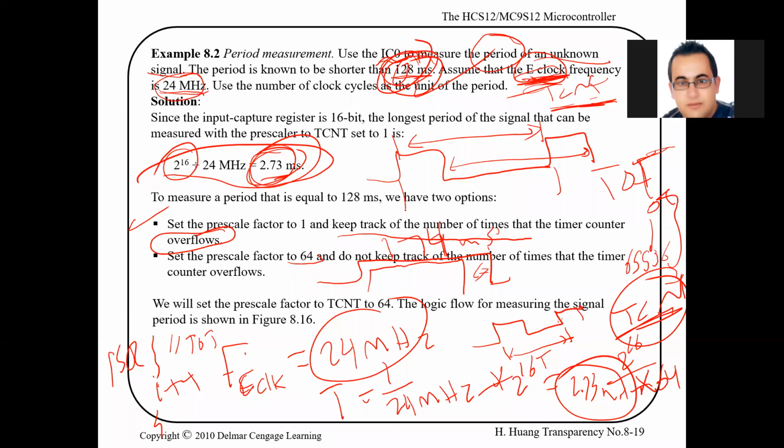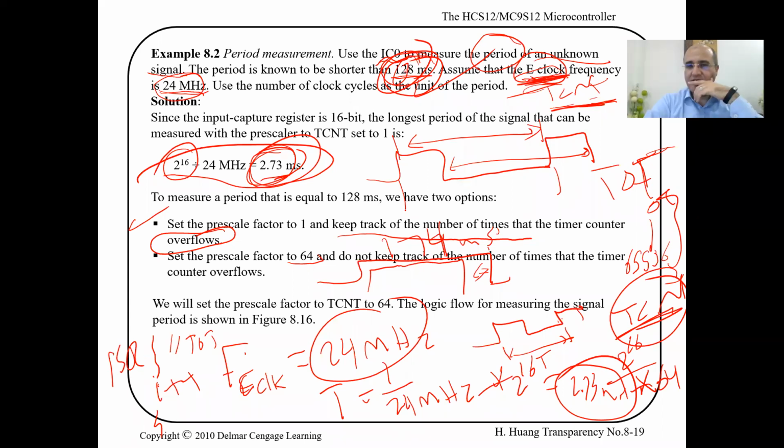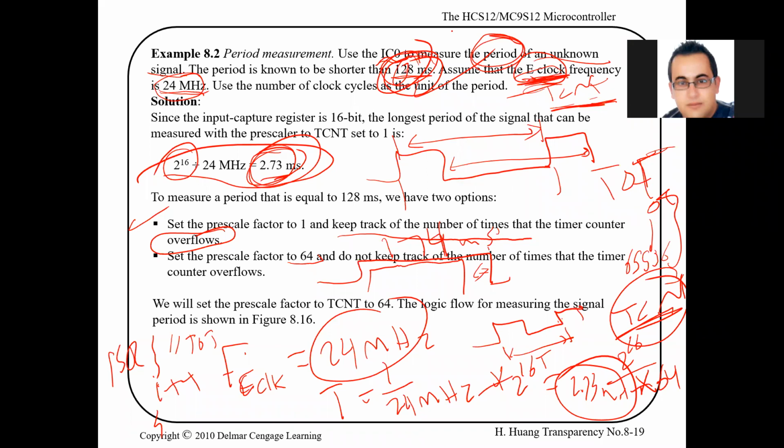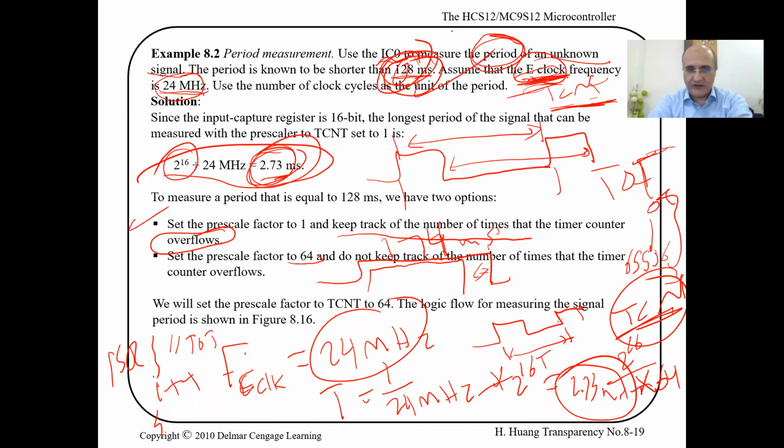But the example is about one edge every period, not taking both the rising and the falling edge. If I take the rising and the falling, I get the pulse width, which is half the period here. Yes. So you will need to take 2 rises or 2 falls to measure the period. Not one on a rising and the other on the falling. Either all rising or all falling.